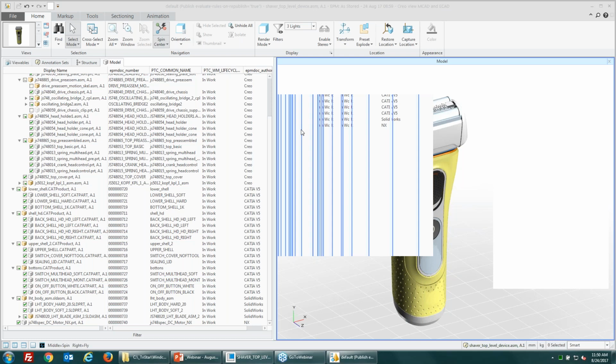Another question was, if we update to the new license server, does the license file need to be updated? No, so the license server is backwards compatible. So if you're using Creo View 3 or previous versions, you don't need to update the license. For those softwares, you can just use the old license server.